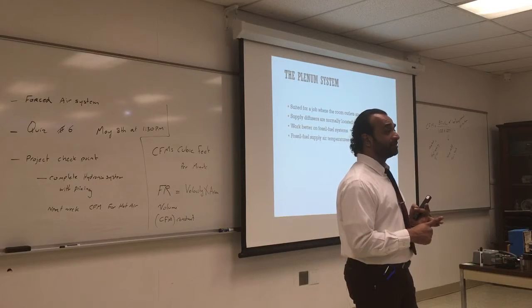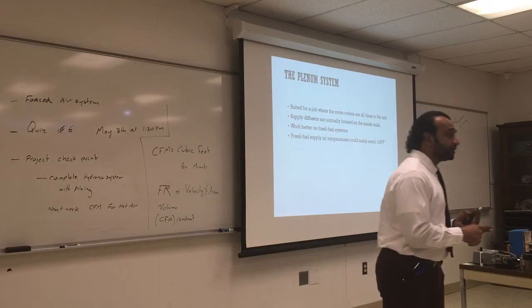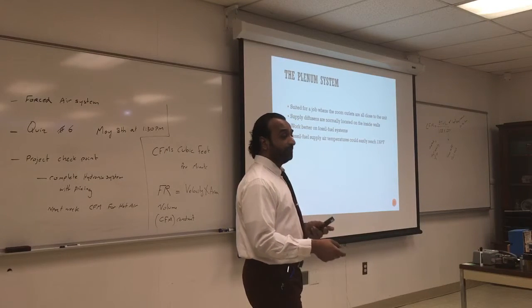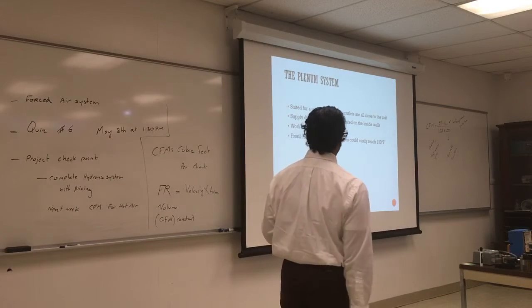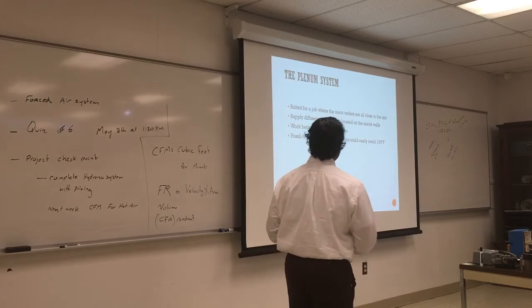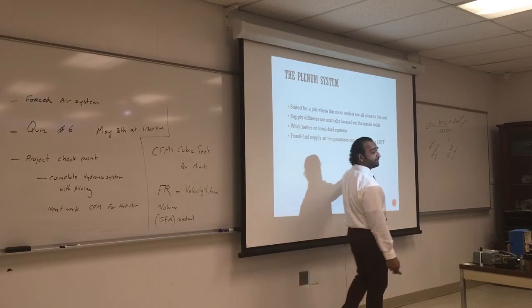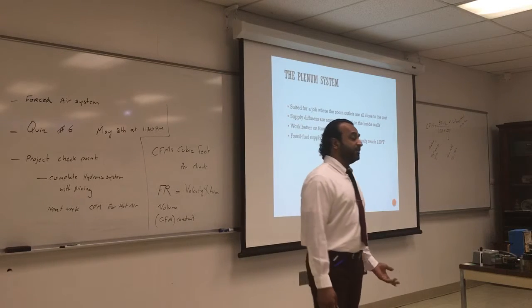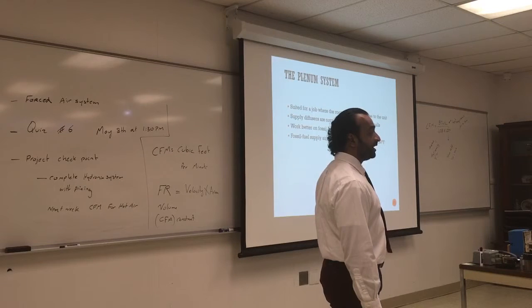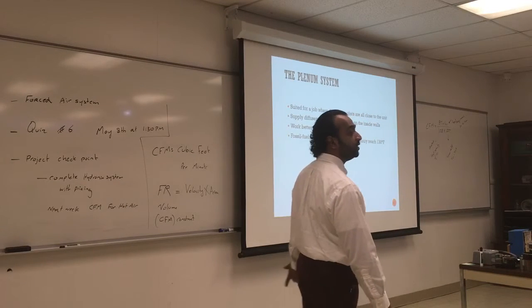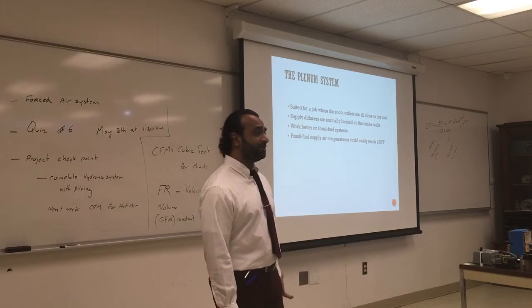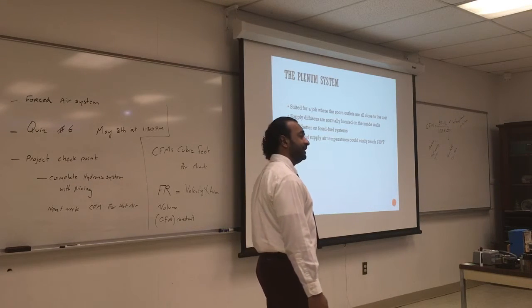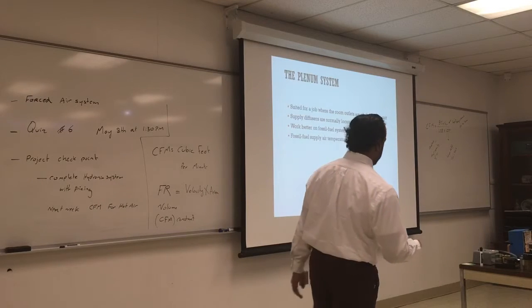it's not going to be as hot as fossil fuel burning. So it's going to be lower. It's hot enough for you to achieve the room temperature, but it's not hot enough to go for distance. We can easily have 130 coming out of the air handling unit, but for central air you cannot get this high, maybe 100, 110, 90, which is enough. What is the required room temperature? 75. So if you supply air between 85 and 95, you can reach that temperature.